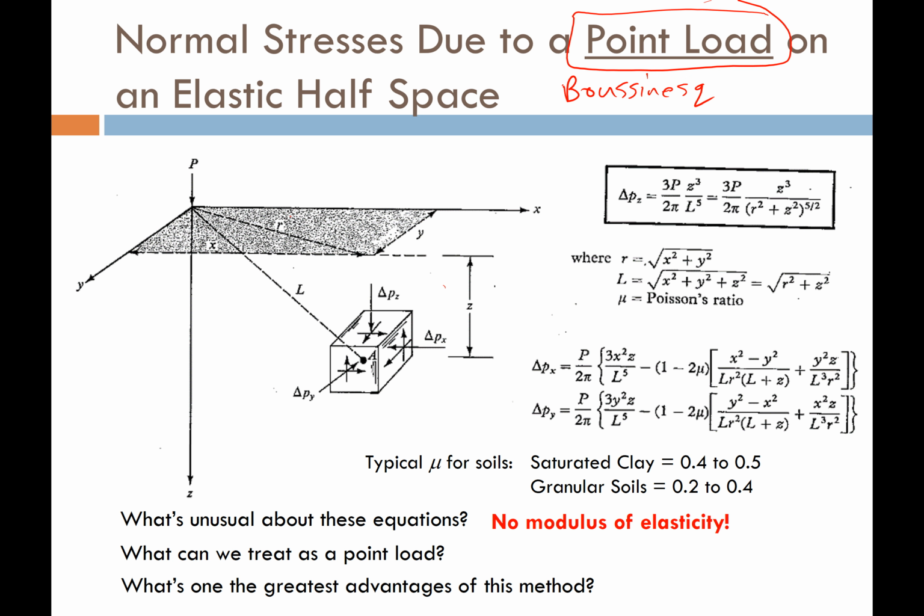Did you hear me, folks? Soil type does not matter when we talk about Boussinesq and elastic solutions. The nice thing about that assumption is that I don't need to know what is actually there to estimate the induced stresses from some load that I'm applying to the ground surface.